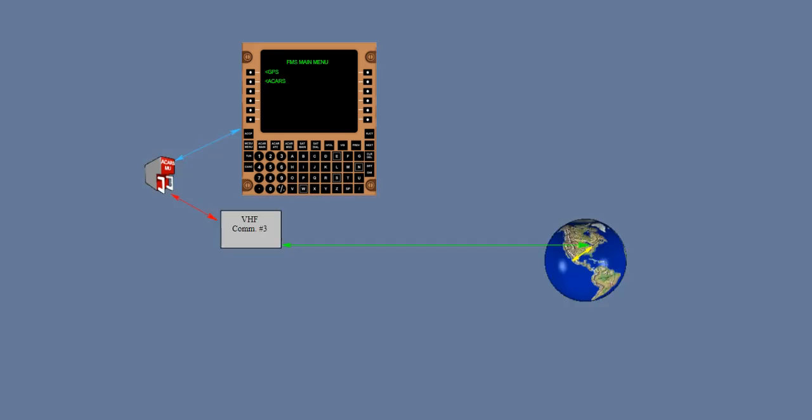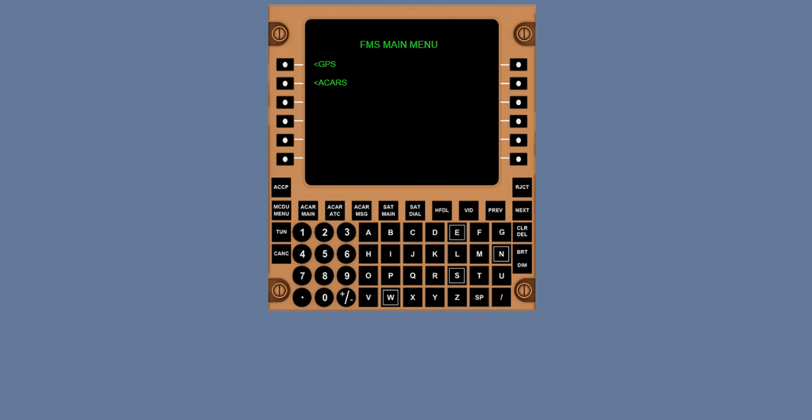Now you've learned that the ACARS MU normally transmits and receives data through the number 3 VHF radio. Therefore, the MU tunes the appropriate frequency and transfers data messages without input from the crew. With the installation of the new generation ACARS, you'll be surprised at how many additional useful features are now available. Future considerations may include the ability to communicate with ATC over the ACARS to relieve the congestion that occurs with multiple voice transmissions at certain airports.